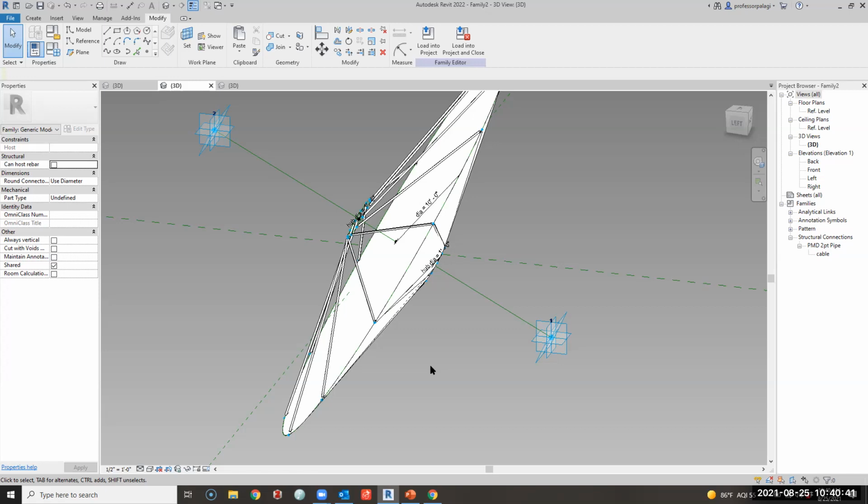This idea of type versus instance. Okay, that is a really important thing to go through here. Type is like, I want this door to be 6 foot, 8 foot, 10 foot. I'm going to tell it that type, and that's what it'll be. Okay, that's great. I want a 2-inch diameter, 4-inch diameter, and I can just change it, and they all become that. If it's an instance adaptive thing, it means every one of them might change. Okay, so when we go that, you just got to be aware because you want something to change every time. Well, do you want to make a type for each one of those, or do you just want an instance one to always adapt to it? Those are two things. You can change something on the way, but that's what we're going to work through.